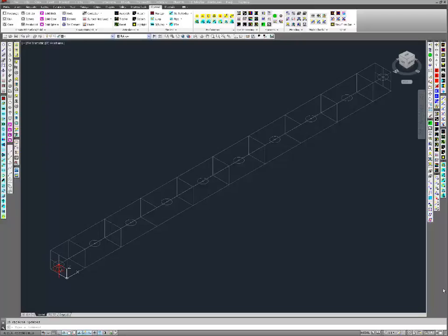This is the TD model I'm going to use to demonstrate some of the concepts that I've been referring to in the video. This model is actually the same one used in the introduction to the optimization video, which you've already seen, so I won't go into too many details here, except this time we're not finding the smallest bar. We're leaving the dimensions set and pretending that we don't know what the density and conductivity of the bar are, but that we'd like to back out the best estimate values of those 2 properties from a set of test data that were taken over a 1,000-second heating transient.